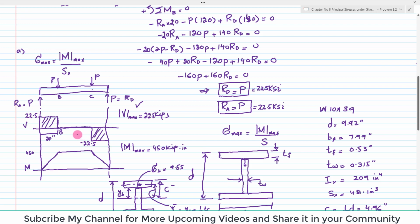Now we will draw the bending moment diagram. For bending moment, you can see from point A to B. Clear? This is the shear force diagram, and the area under the shear force diagram is bending moment. So you can see this is a rectangle, so area of rectangle is 22.5 multiplied by 20, which will give you 450 kips into inch.